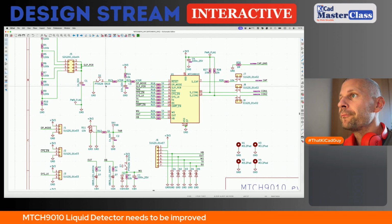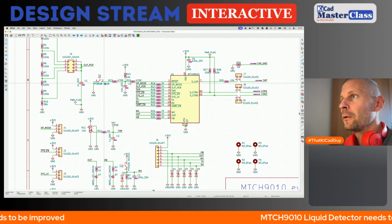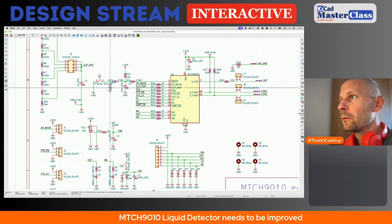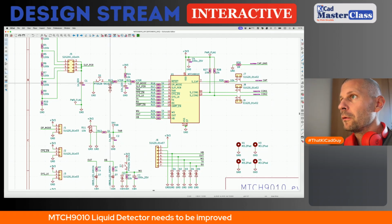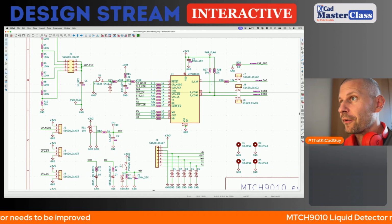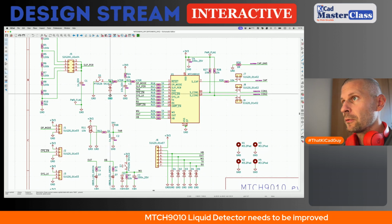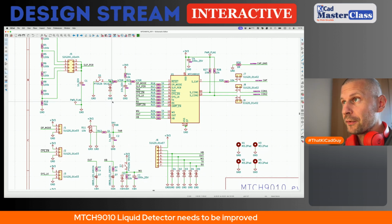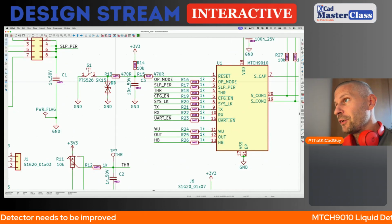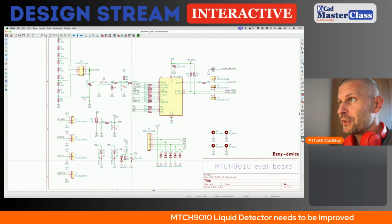Like this. And for the reset port as well. Because wherever a human touches the PCB or any component, the discharge event can happen. And we don't want to discharge charge from our bodies into the IC.